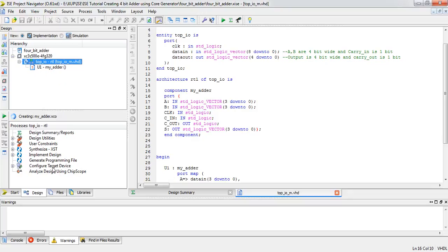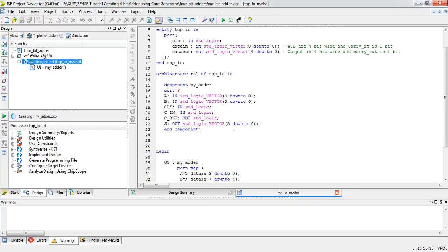It is generating the IP from the local directory into your project directory. The IP which we have generated will have these ports, which are instantiated in the component. A bulb icon has appeared right here.